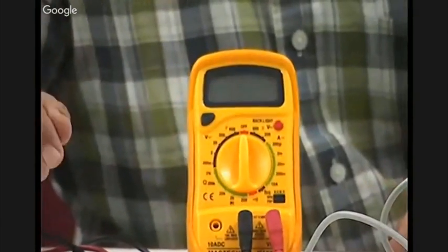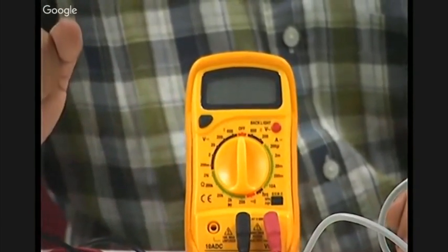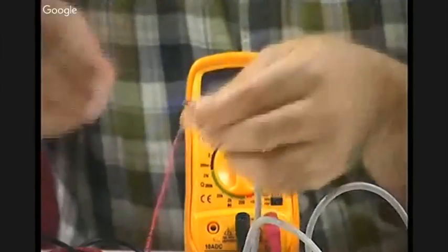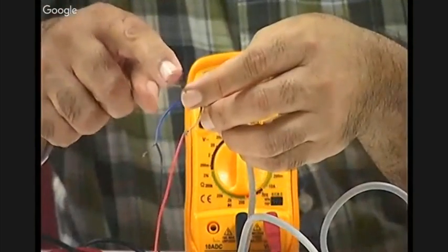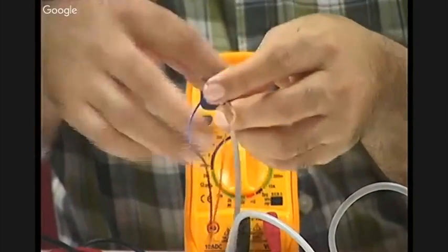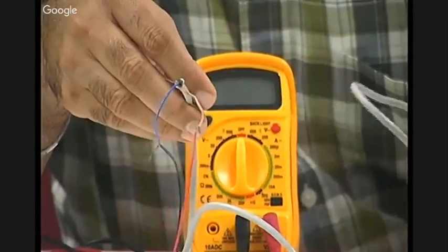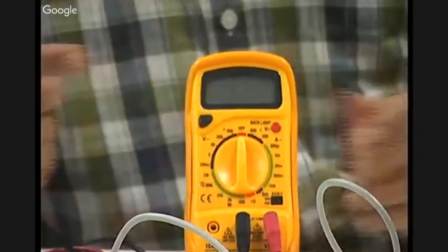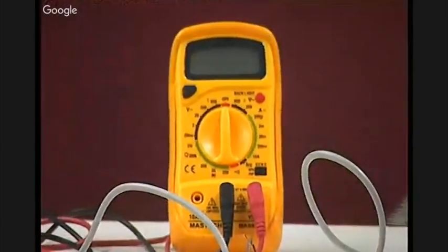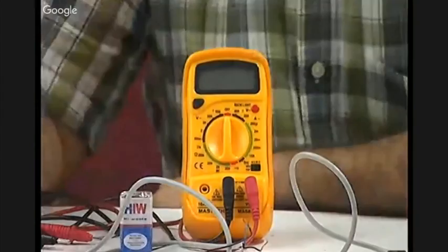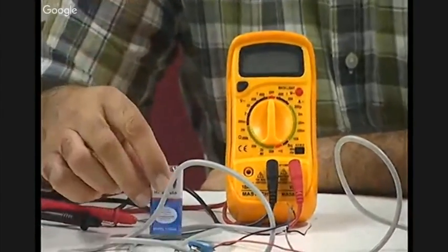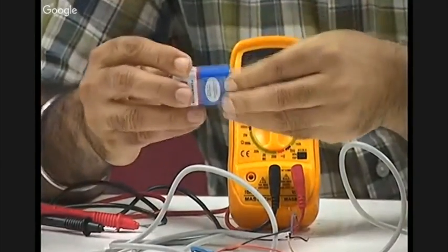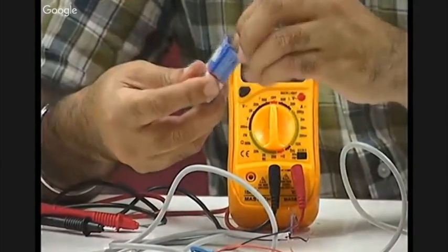Okay. So we'll make use of a multimeter to detect the output on the output terminal of the sensor when an object comes near it, right? Because we'll be using a simple 9-volt battery, a 9-volt cell, the output will also be at the most 9 volt.